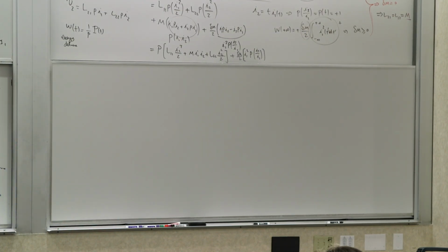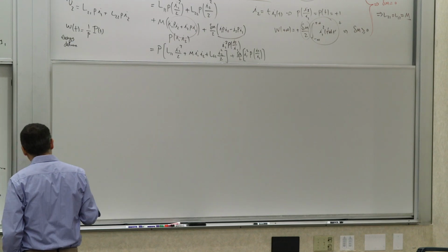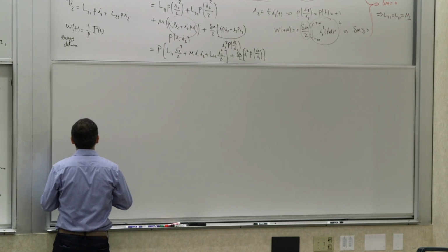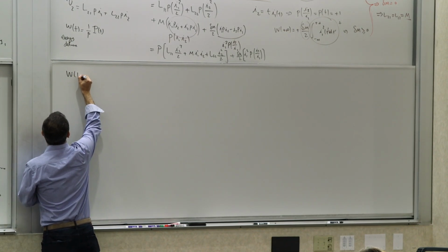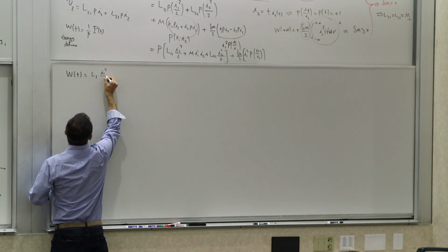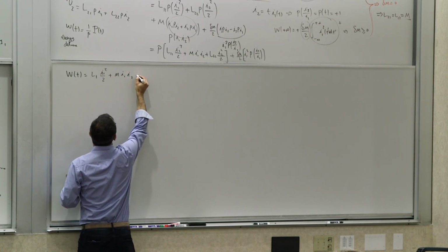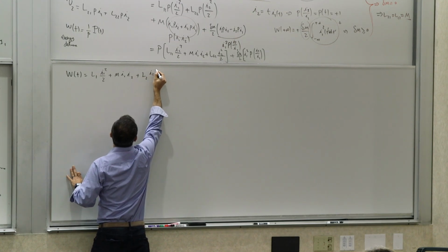Anyway, okay. So, what else can we say about the inductors? Now, this calculation that we did is actually quite useful, more than the proof. I think this is probably a more useful part of it than the proof, which is that now that we know that delta m is 0, we know that the total energy delivered to the inductor is simply L1 I1 squared plus m I1 I2 plus L2 I2 squared over 2.